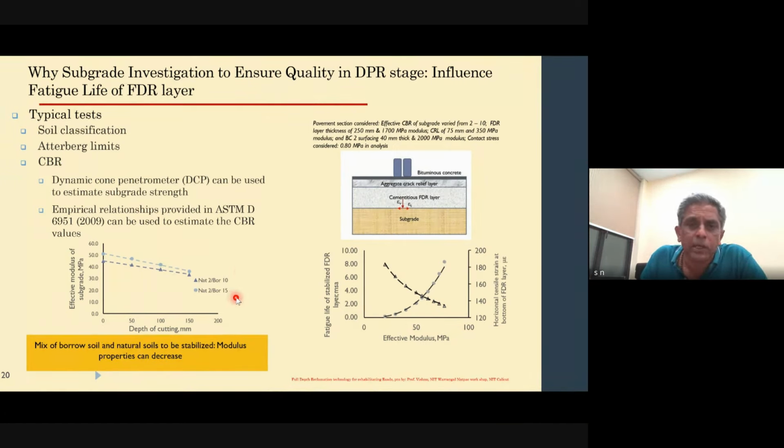Now, pre-construction, one of the earlier steps that you have to do is to identify the finished road level. That becomes very important because you need to know what exactly is going to be the finished level. I'm just going through the same example that I have given earlier. The thickness is about 0.2 meters, a 3.75 meter road widened to 5.5, and the total width of the base comes out to be 5.65. Now here the thickness of your base is 0.25 or 25 centimeters, and let us assume that the existing road level is 101.30 meters. This is the reduced level of the existing road.